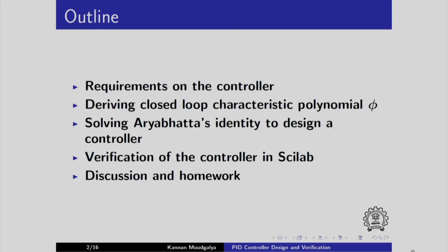We will state the requirements on the controller. We will derive the closed loop characteristic polynomial phi. We will solve the Aryabhata's identity to design a controller. We will verify the controller in Scilab, and we will conclude with a discussion and homework.